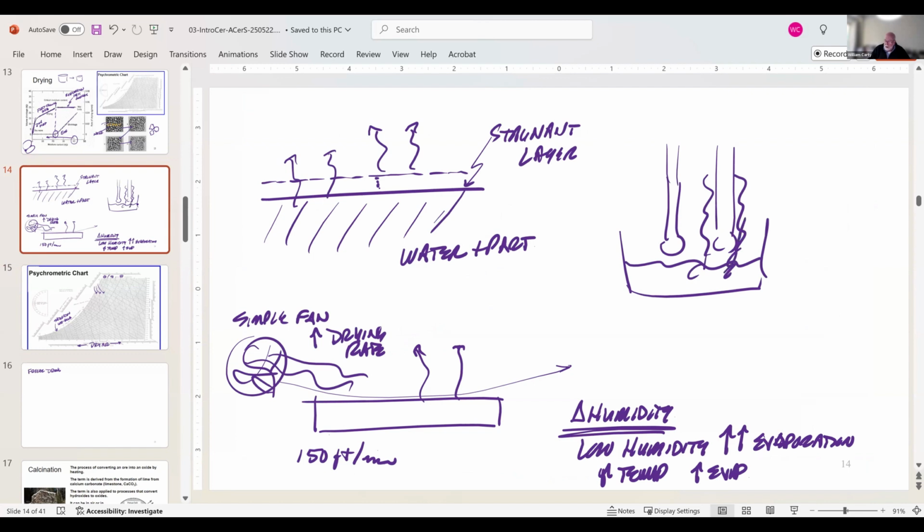So it's capillary action evaporating water in the sock. This is the wet side and the dry side. And here's your temperature. This is your dry bulb temperature. And in the wet bulb, it sits here because this is evaporating and you get evaporative cooling. By looking at the ratio of these two temperatures, you can determine how much evaporation rate there is, and you can calculate the relative humidity.